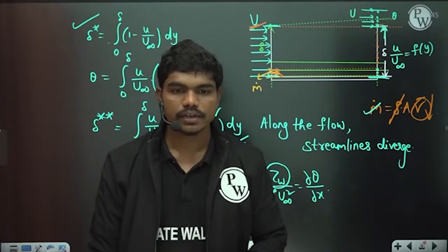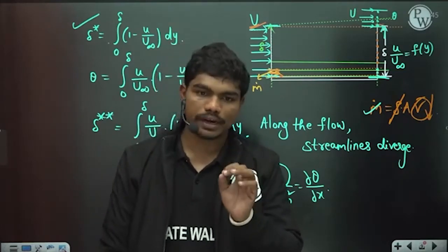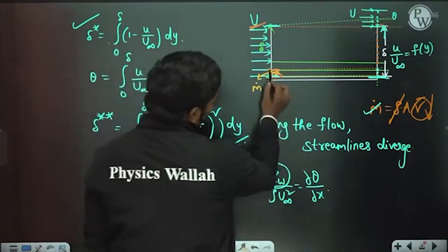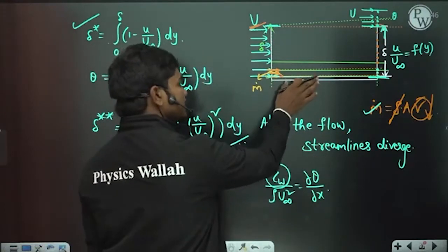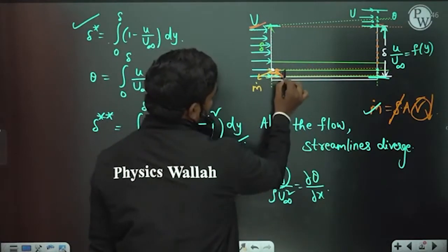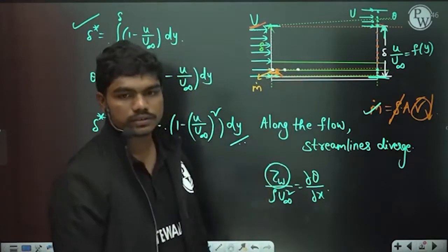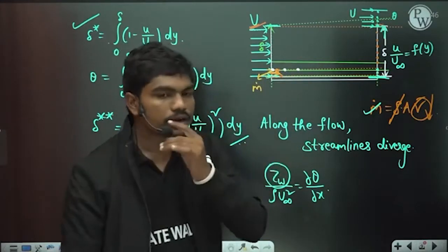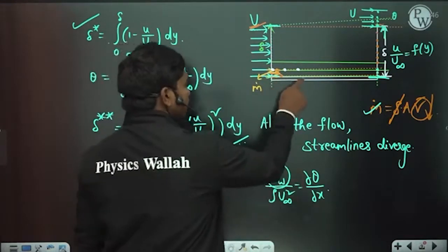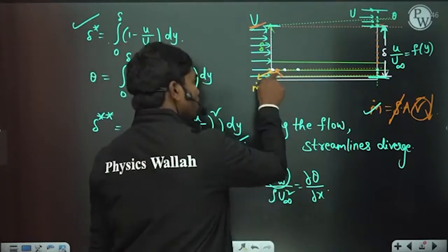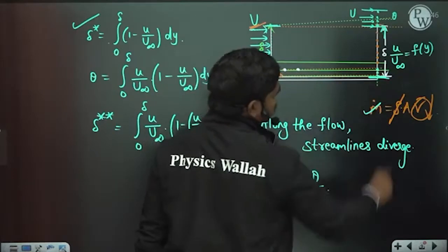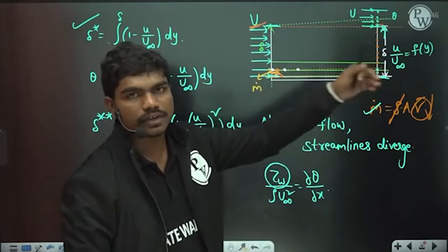I would like to tell you one very easy point. Try to understand the case. When you apply brakes to a vehicle, or whenever the fluid touches the plate, try to understand this concept clearly. Let us suppose you take 2 points here. Whenever these layers come onto this plate, this layer will start to slow down, yes or no? Then obviously the velocity of this layer keeps on decreasing, and finally it comes to some steady value and moves at uniform velocity after some time, after the laminar range got transmitted.